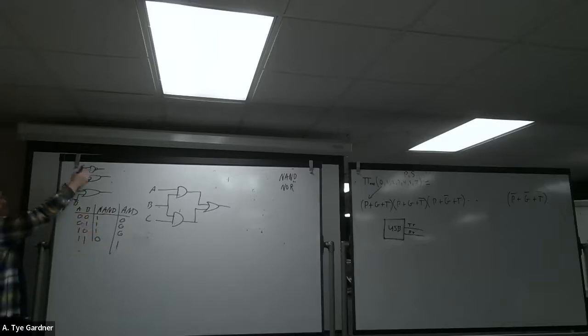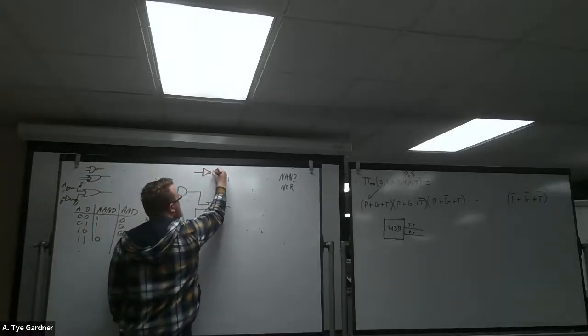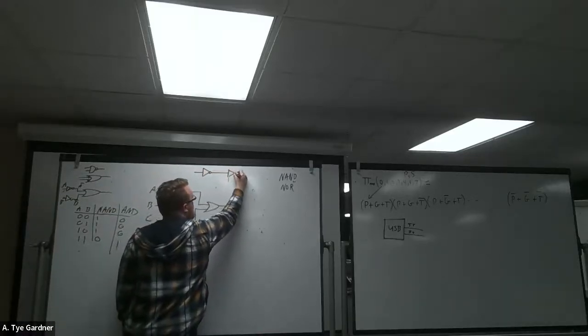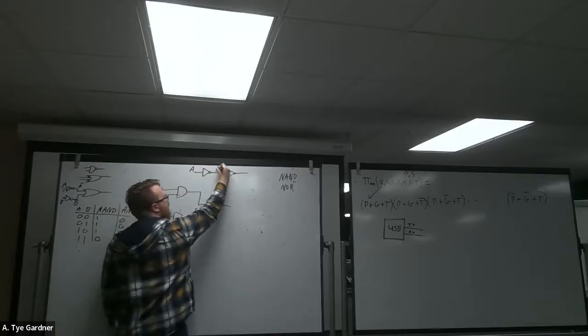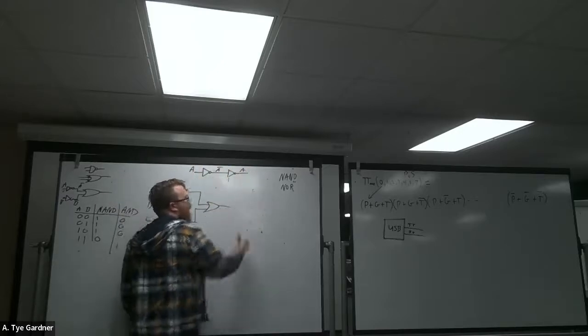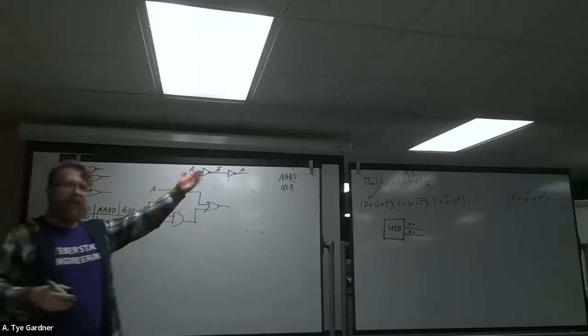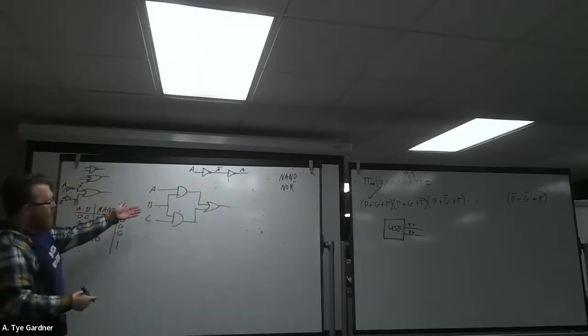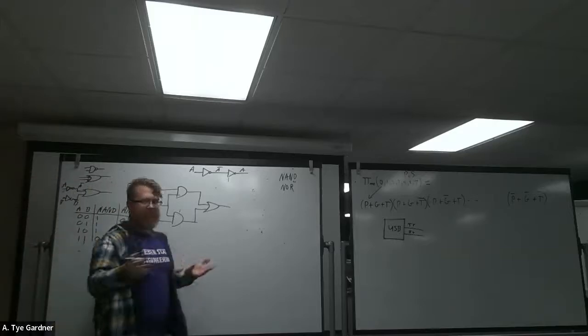So we're going to exploit this property, the fact that these two are the same, and we're going to combine that with the fact that if I stick two inverters and I put a signal A into it, this becomes not A and that becomes A again, right? And they just switch back and forth, A, not A, A. So two inverters are the same thing. And let's go ahead and start turning things into NAND gates.